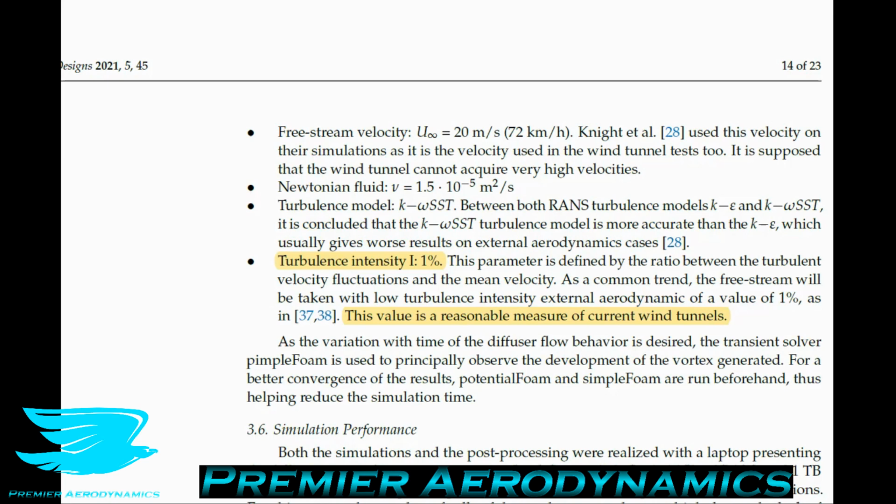So that's very high. However, if you were to drive at 200 kilometers per hour, a 5 kilometer per hour gust is now significantly lower. It's only 2.5% instead of 10%. So it depends on what speed you travel at. Secondly, if you're traveling behind someone in their car, you have the wake from their car breaking down before it hits your car. And that means that you now have a greater turbulence intensity level there.